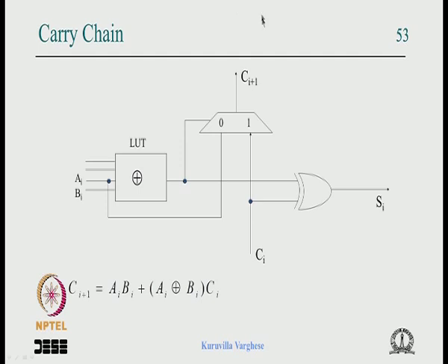There is a mux with the lookup table, and an additional XOR gate which is used for full adder implementation. It can be used for other purposes also, if the location permits. The lookup table output goes to the XOR gate input, and this is available as output.